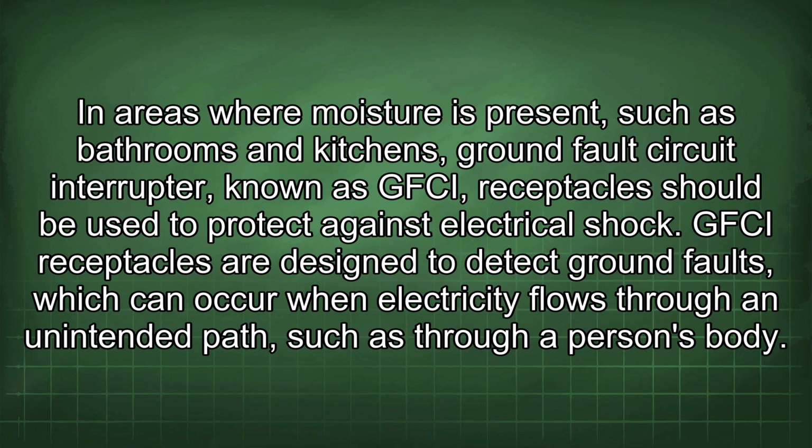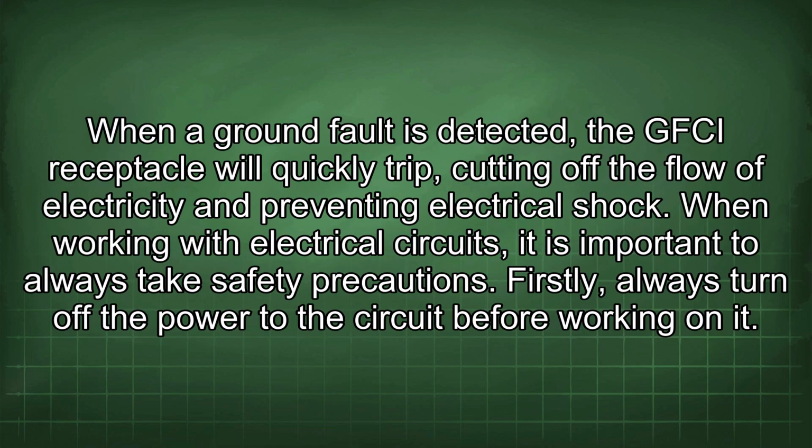GFCI receptacles are designed to detect ground faults, which can occur when electricity flows through an unintended path, such as through a person's body. When a ground fault is detected, the GFCI receptacle will quickly trip, cutting off the flow of electricity and preventing electrical shock.